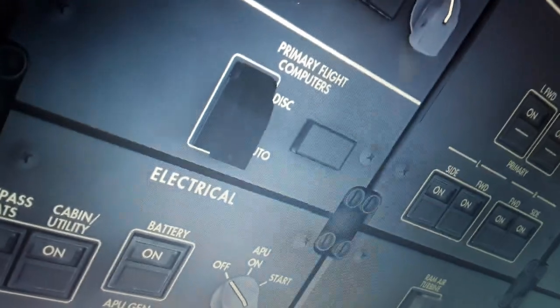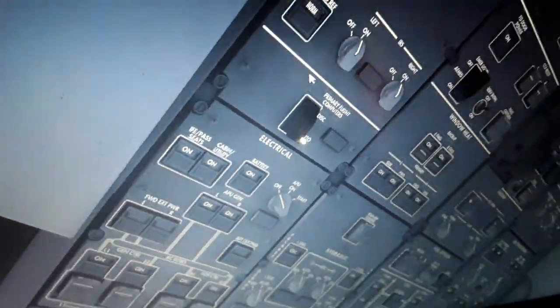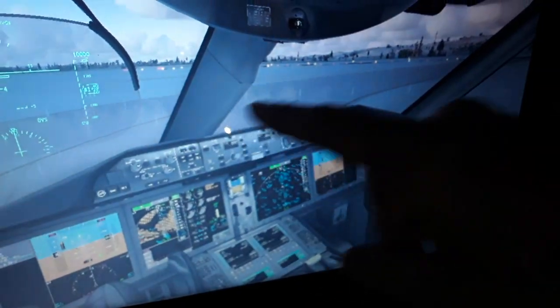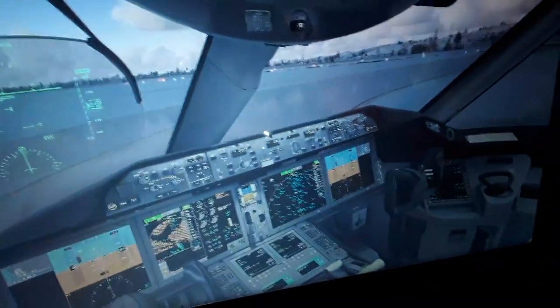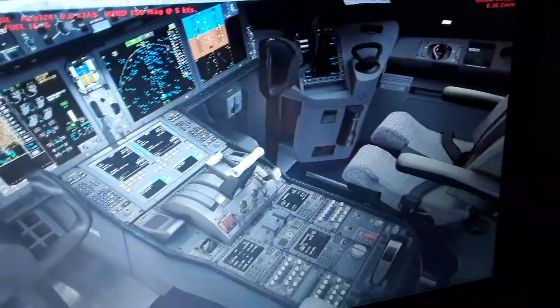We're going to have a malfunction of the flight control computers, and this will degrade from normal. We have the normal, the alternate and the direct law of the flight control computers, like in the Airbus, also the mechanical backup. So it will degrade down the flight control computers function. So you will lose the auto trim from the autopilot and flight director system panel over here, as you can see. So we come down here and we open this.